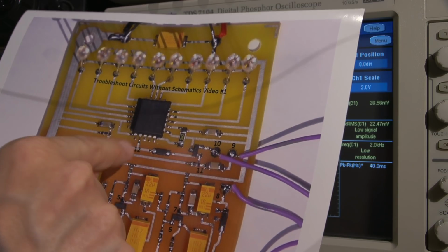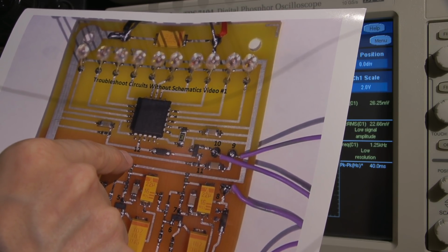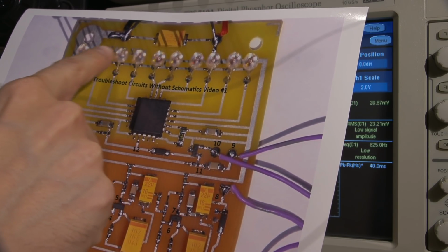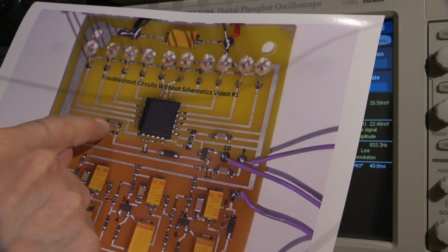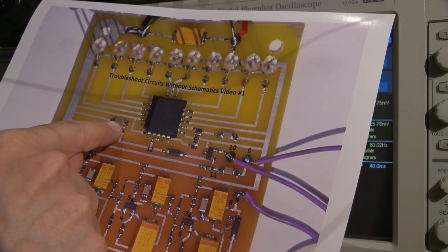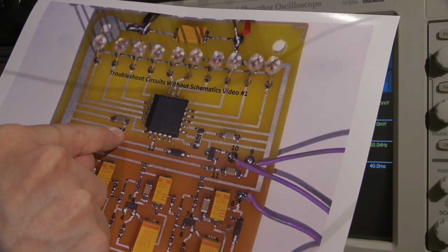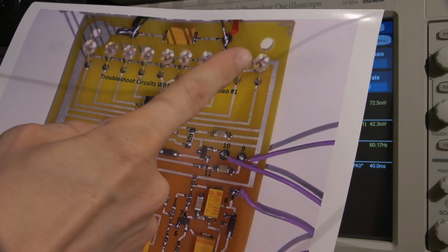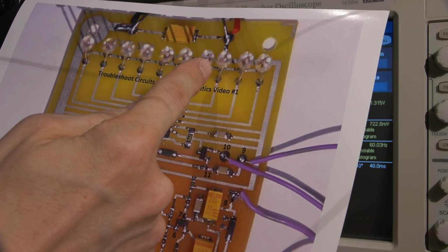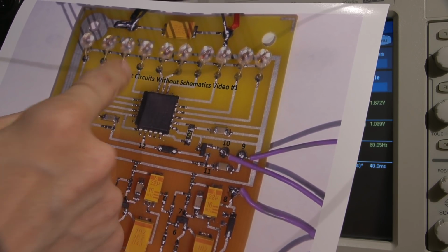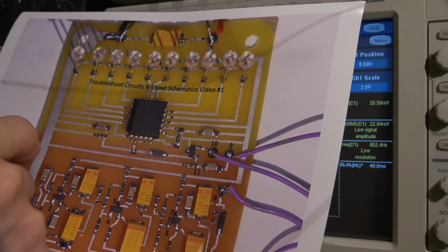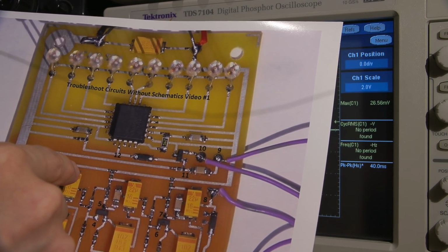Now, the LM3914 needs a DC level in order to make this basically go up to whatever LED we want and then come back down again. This capacitor here is just acting as a filter for that DC level, and we have a bleeder resistor here, which gives us a decay time. If we didn't have this here, it would come up and it would slowly drop off. So we want to discharge that capacitor fast so that we can make that level on the LEDs drop again.